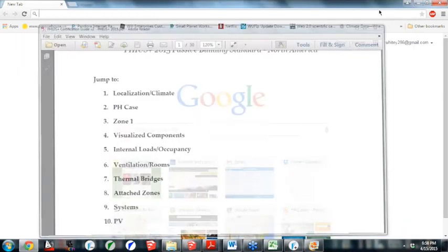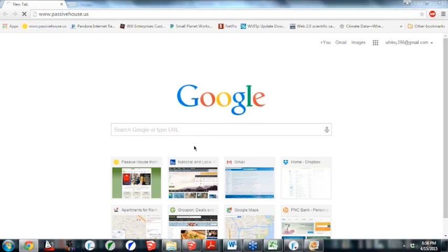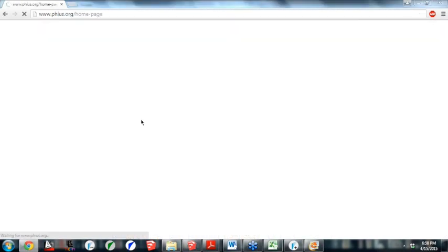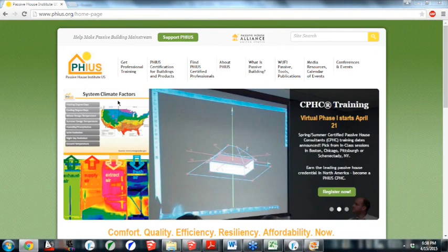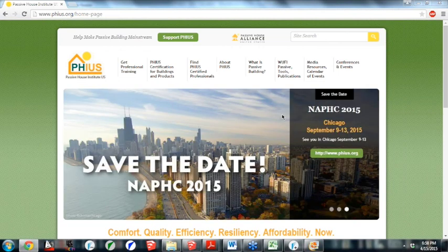Is there an ability for lighting controls to reduce lighting electrical energy through daylight harvesting or occupancy sensing? Not for residential right now. For commercial, yes. Or not commercial, but non-residential.